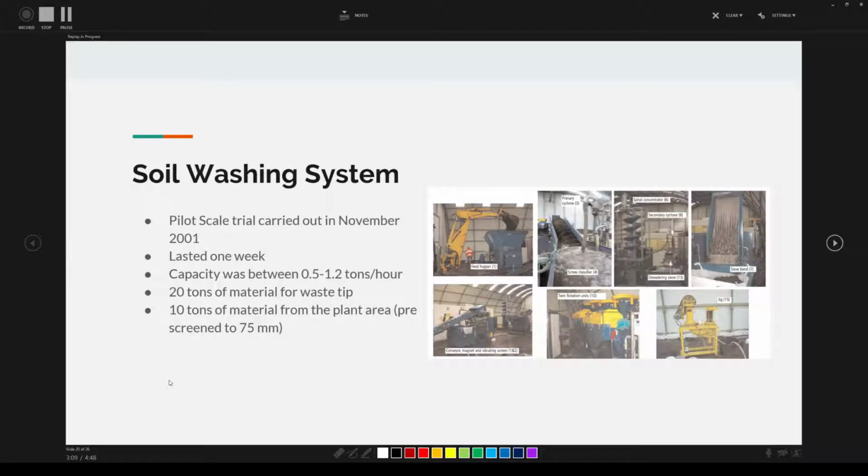So a low specific gravity product, which contains most of the contaminants or organic, light minerals, coal, oil, tar, etc. A heavier SG product, which, if clean, is dewatered as a final product. Alternatively, if still above the cleanup target, is further processed by froth flotation. And then a middlings product, which is either repassed through spiral concentrator or treated using downstream froth flotation to remove the contaminants.